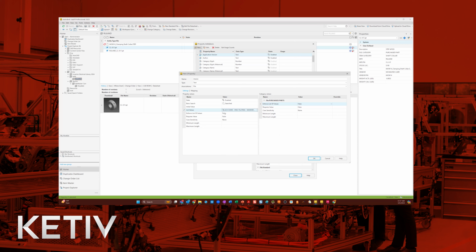See, enforce a list of values? No, we want people to be able to populate that. Want it to require a value, so no initial value there. Definitely want it to be all uppercase and no min or max length. So that takes care of all the conditions that we're wanting there for the data standard on the front end.